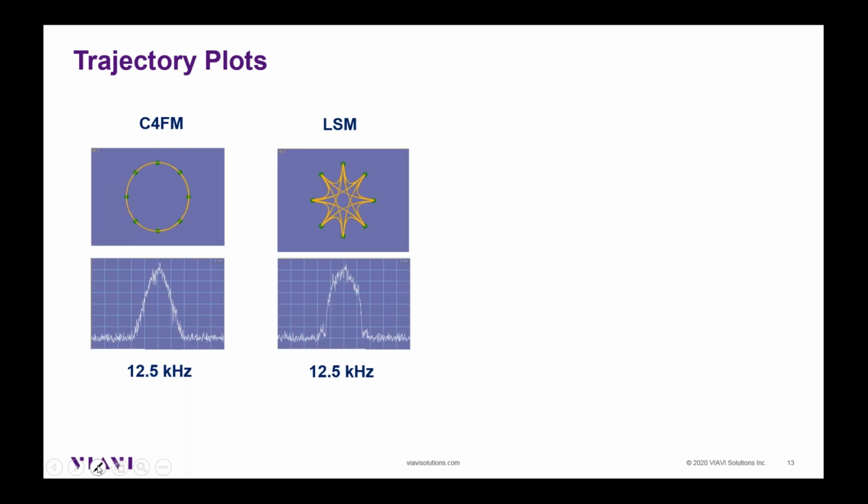So this is an example of linear simulcast modulation. This type of signal is only transmitted by a base station. It's a complex waveform where the power varies between symbols. So on that distribution plot, when it's going from one symbol location to another, the power actually droops from one symbol location to another. But at symbol time, it's always at the proper power level or the same power level.